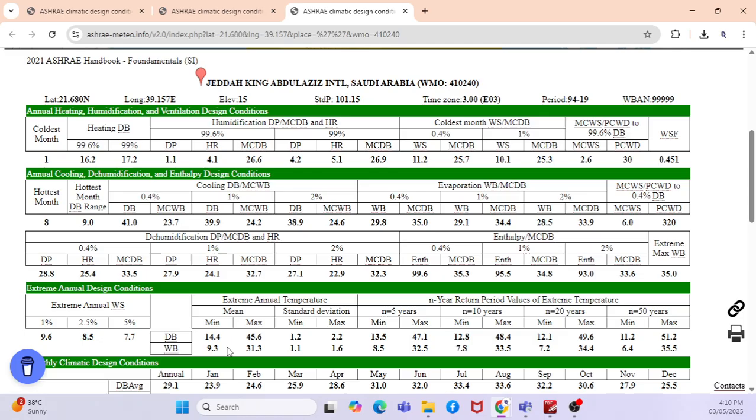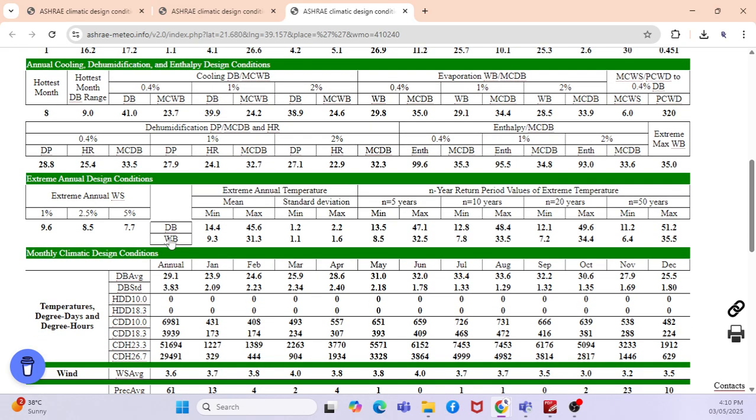And also you can calculate the specific volume, and you can also calculate the dew point temperature, the specific humidity or humidity ratio, correct? Yeah. So if you know these two values, you can go to the psychrometric chart and you will be able to.